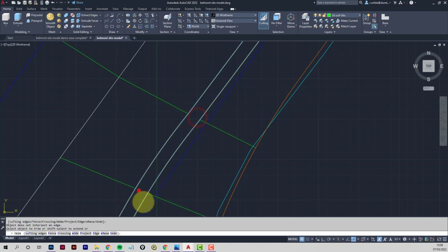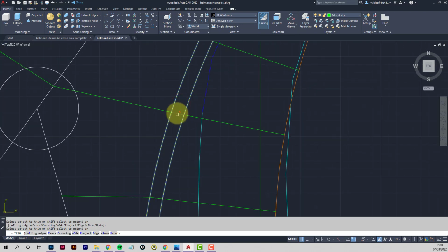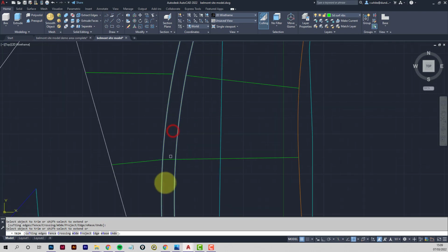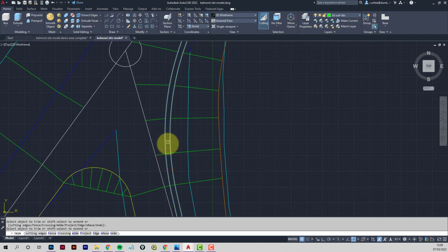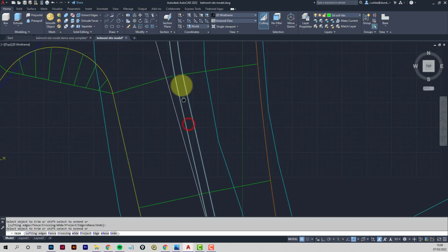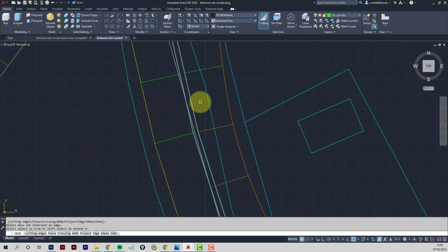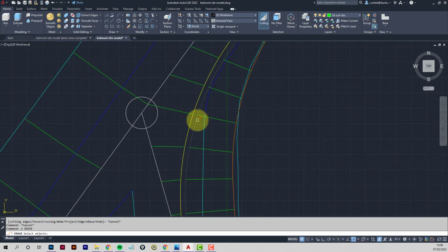This should be a bit easier now. When you get to the end, sometimes you have to extend the yellow line, the trimming object, because it doesn't quite touch the last of the ribs, because these are drawn generally freehand, so they're not perfectly perpendicular or anything. So that's that side done, so that can be switched off.